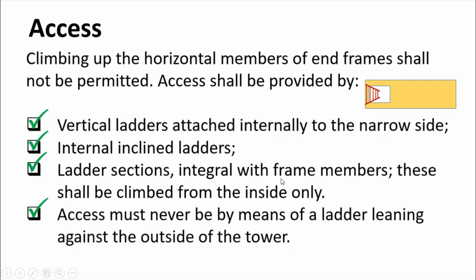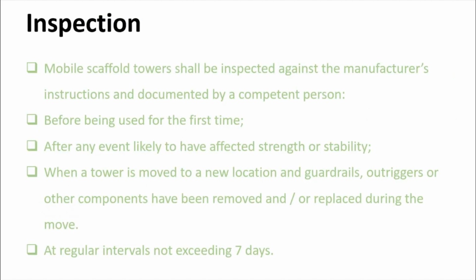Access must never be by means of a ladder leaning against the outside of the tower. This will make the scaffold unstable due to the imposed live load when you are climbing on the ladder. So it may trigger accidental movement of the tower due to your weight.